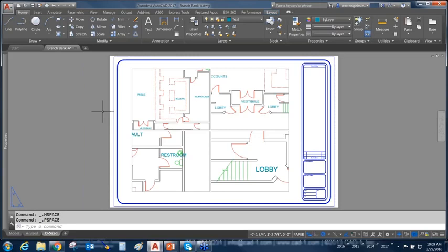However, having said that, if you conform to the architectural graphic standards of drafting, if you're submitting this to an approving agency, if this is a construction document of any kind, then what you see in front of you is a no-no. I've got text of all different sizes in here. Now, all of my annotation is supposed to conform to just one size.